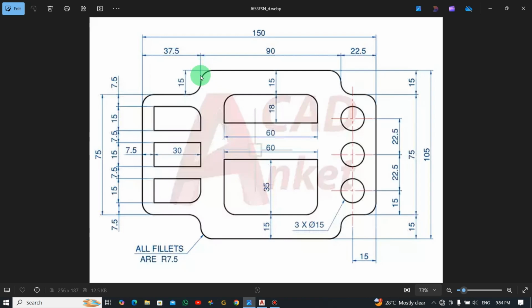Now let's start from this side. When you look at the drawing very well, you can see it's a square, something square. From this side to this end side we have the measurement here. All the measurements are in millimeters. From this side to this side is 90 millimeters, and then the distance from this place to this end is 22.5 mm, and then this total height is also 75 mm.